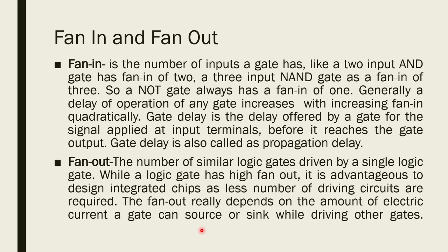The operating temperature of the device will be increased. When the temperature is increased, the reliability of the device will be reduced, and eventually the device will fail. Propagation delay will be increased, and it may go above the specified value. The output rise and fall times may also be increased beyond the given specification.